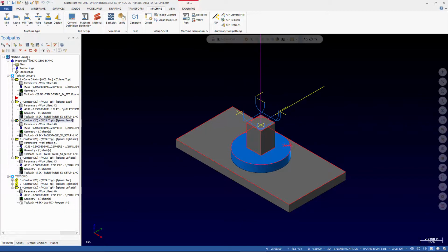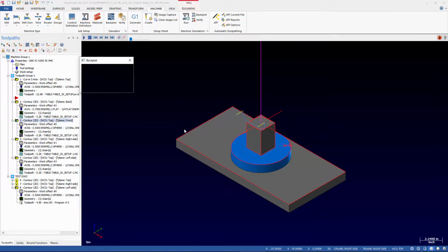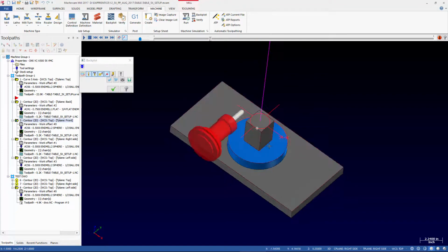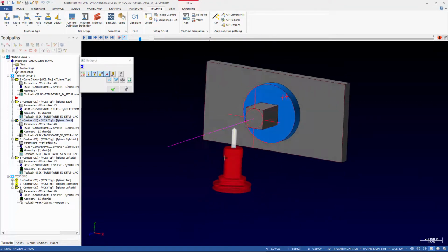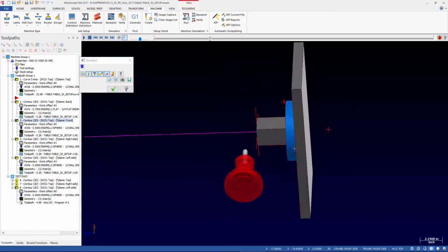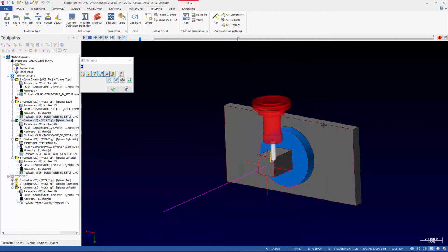So if I look at this toolpath on the front, in order for my tool to reach this side of the part, we have to first rotate to -90 because we have a limited travel range on that secondary axis. And then, because the tool, you can see here, is upside down, we're going to have to end up rotating 180.